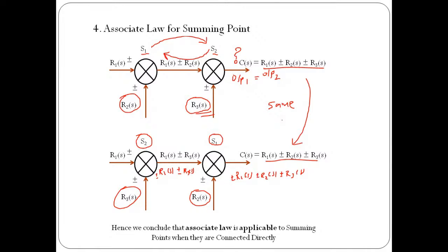Whenever we apply a block diagram reduction technique rule, the output of the system should not change. Whatever output the system generates before applying the BDRT rule, the same output the system must generate after applying any rule of BDRT.